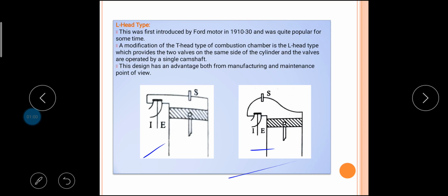The main objectives of Ricardo's turbulent head design, from this figure, are to obtain fast flame speed and reduce knock. The main body of the combustion chamber is concentrated over the valves, leaving a slightly restricted passage communicating with the cylinder, therefore creating additional turbulence during the compression stroke.